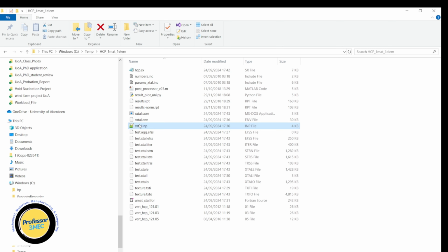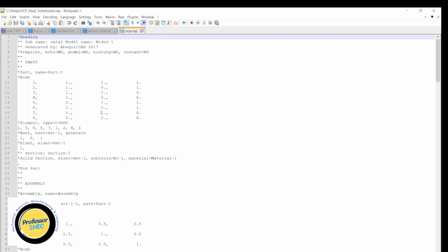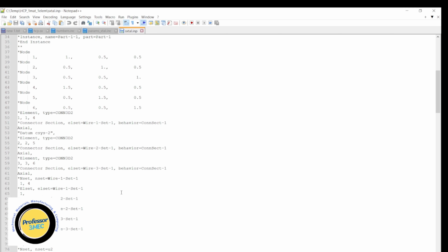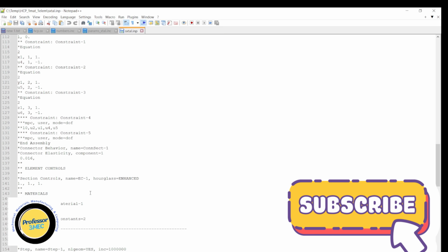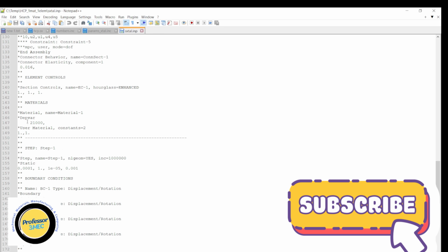Then we have an input file. In this case, we have one element model with uniaxial loading, which you already are familiar with. I have many videos on how to create a uniaxial model based on that. The only difference here is you have to define a material card with the dependent variable of this, and these variables are dependent on the number of state variables which are involved.